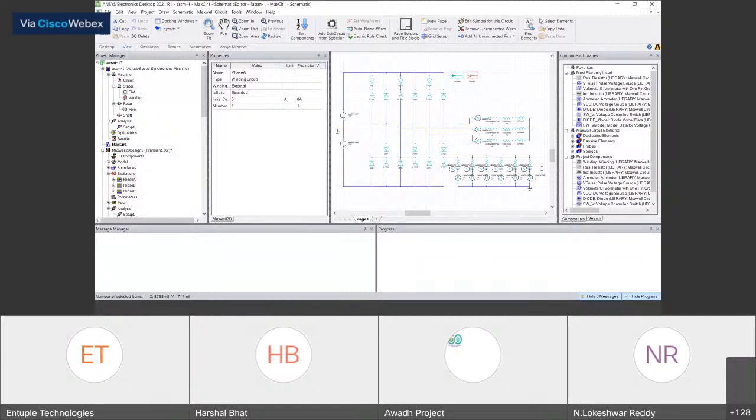But say you have a power electronic board on the PCB passing a high value of current to your IGBT switch or a MOSFET. Then looking at the stress, the current distribution inside that trace, and the losses inside the trace, all of those things can be done in Maxwell.